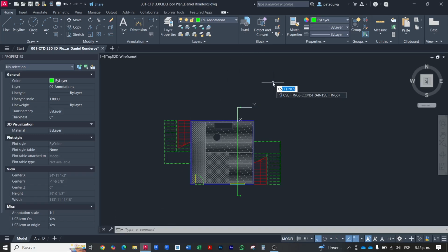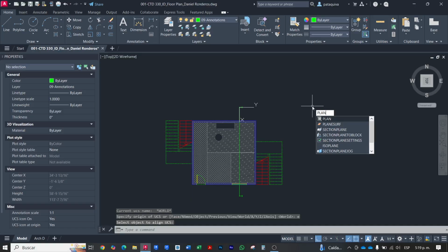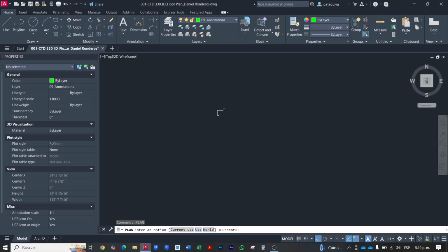So I'll just select this element and see that the UCS shifted from its original position that was around here. I'll go back. See, the UCS was here. So by typing UCS, enter, the letter E, enter, and selecting an element on either side, see, it rotates. I'm selecting it here. Now I'm just going to type in plan, enter, and I'll align it with the current UCS.